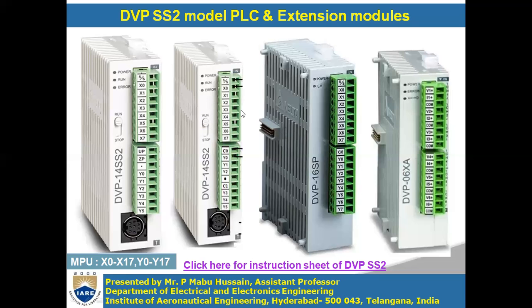Okay, on the backside of this you will have one slot. Under this slot you will place this, so that these two are joined together, and in total you will have 14 plus 16, 30 IO devices, IO terminals. Now if you add this device to this PLC, you will have only digital inputs and digital outputs.